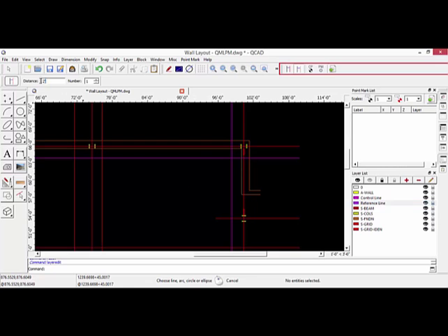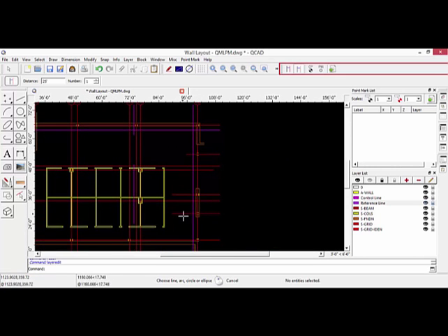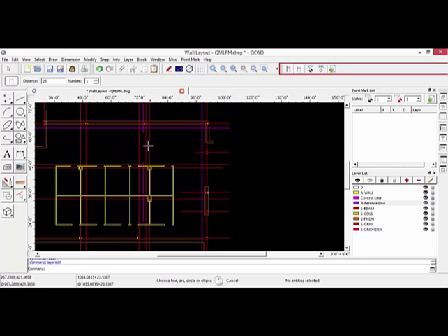And I want to specify a particular distance of reference line. So you want to get a good distance between these 2 points so the lasers can actually measure a good point. So I'm going to specify 25 feet off of my first line. And again, I'm going to put my cursor real close to it. All right. And once I establish that, I'm going to click. So you notice that it's there. Now the line type is different, as you see there.